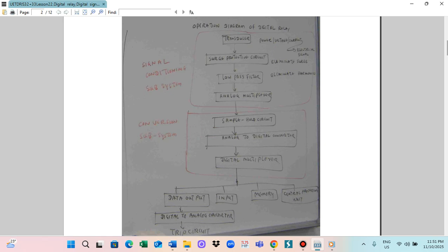So this is where we operate the relay. The operation should be in a sequence, a sequence of relays in the power line. So these are relay 1, relay 2, and relay 3 like this. When a fault happens here, relay 2 operates first, this one operates second, and this one operates third. This one is the generator.